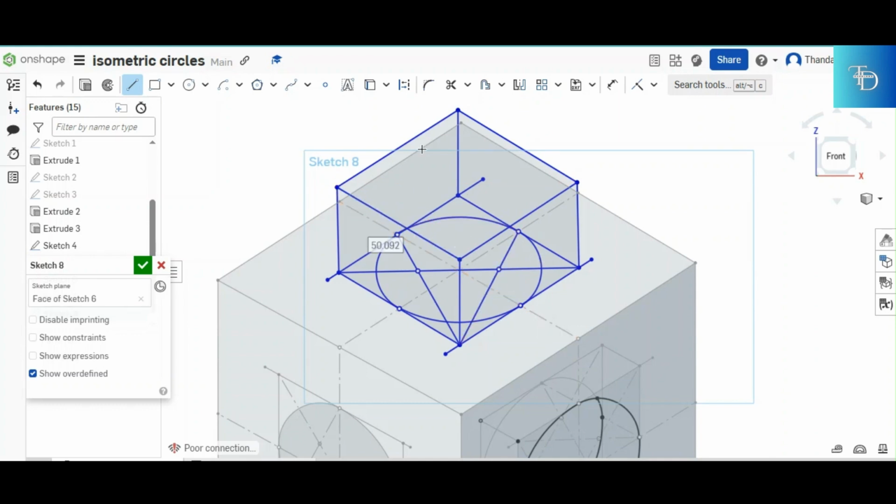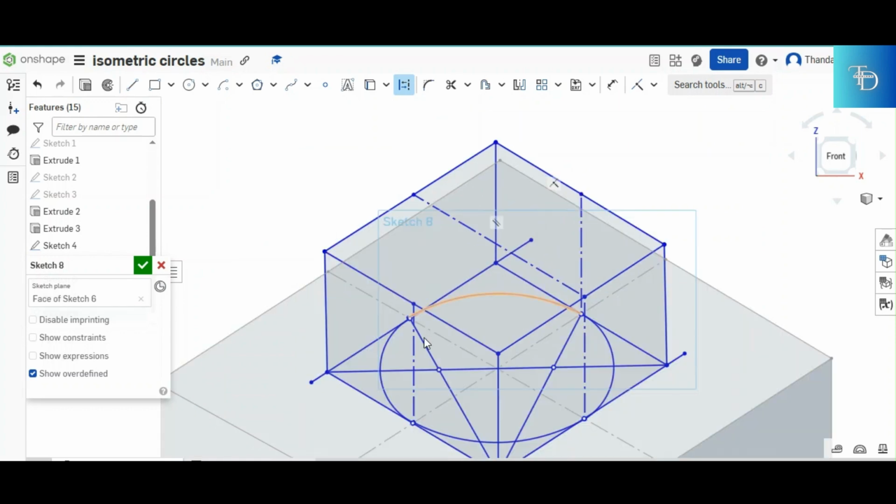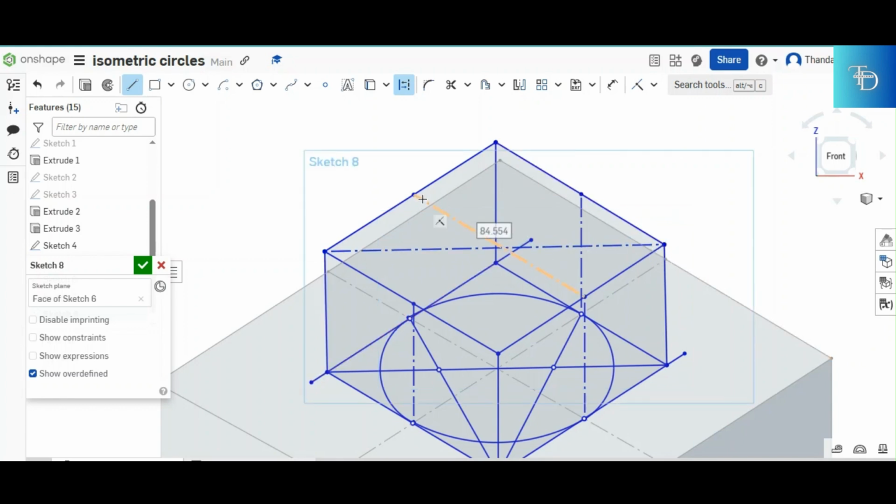Just like that. And then the next step, you do the very same thing that you did when we were working with our right side right here. We transferred our original centers to our newly created square. So you do the same thing even on this side. You transfer the center to your square. Alright, after transferring all the centers, you know the drill. You join what? The 2 points that have a greater distance apart, which in this case is the very same point as our bottom square. Right there. Just like that.